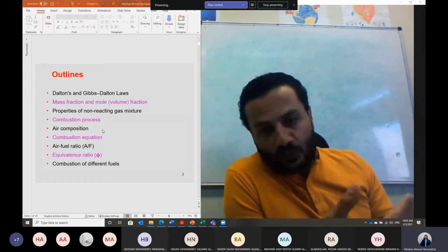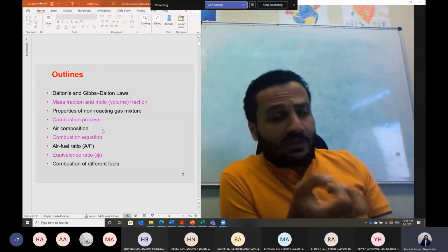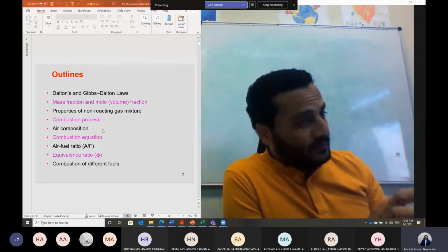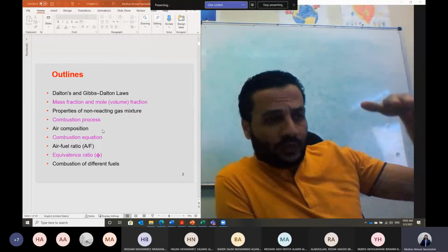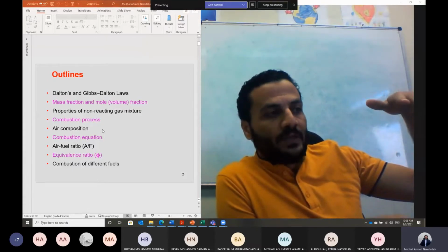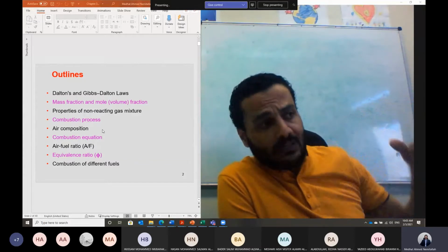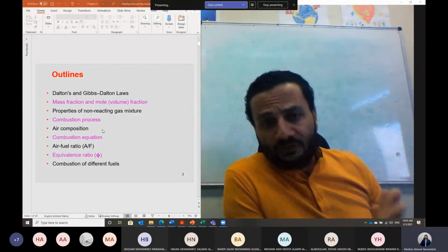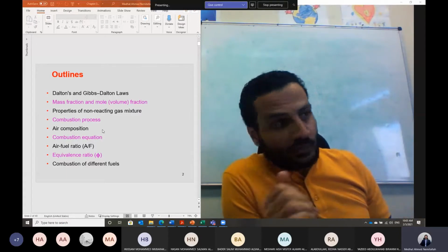Theoretical, شباب, or stoichiometric, that means this is the fuel to air ratio where we have the amount of air that is just enough to burn the fuel. We call it the theoretical. If we have more air, we call it excess air. If we have less air, less than the theoretical, then we don't have enough air for the combustion, so the combustion will be almost incomplete combustion.